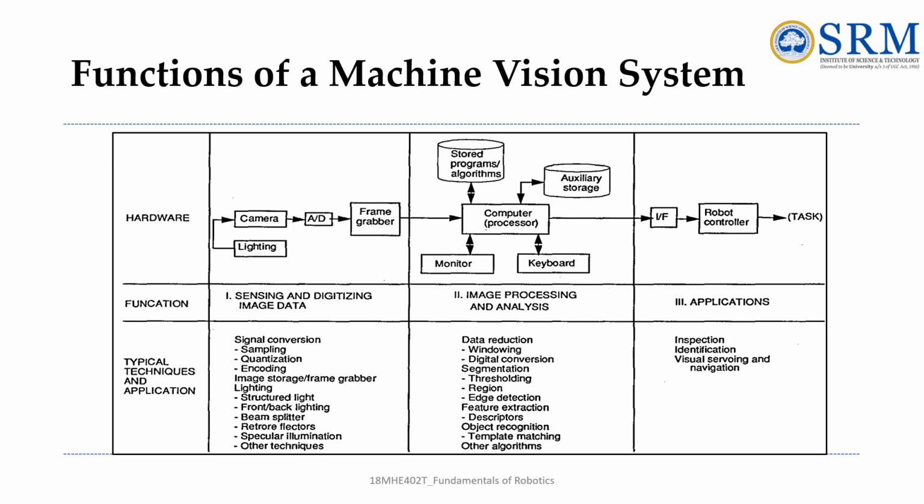The third technique is edge detection. This considers the intensity change that occurs in the pixels at the boundary or edges of a part. Given that a region of similar attributes has been found but the boundary shape is unknown, the boundary can be determined by a simple edge following procedure.